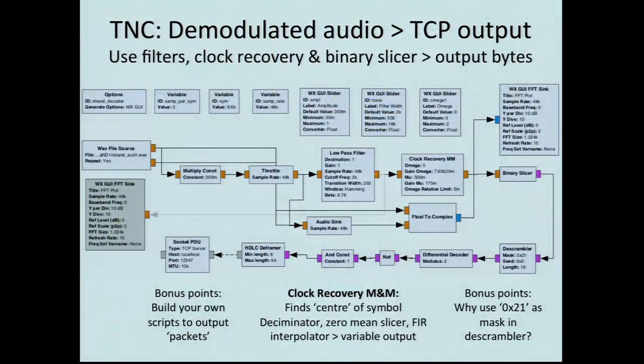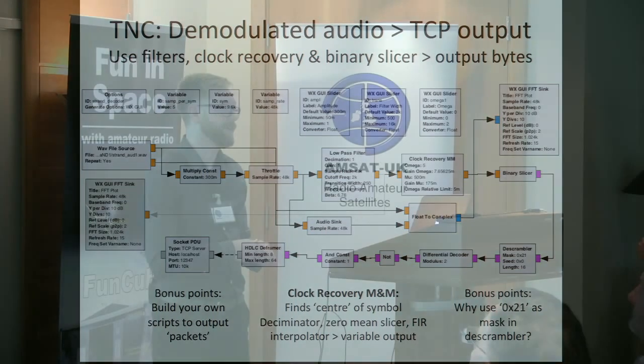Just some examples. The biggest thing that I've worked on is 56 mega samples per second. So you're looking at, at best, hundreds of megabits per second, and I use an FPGA for that. On those FPGAs, I'm doing most of these blocks that you would see in these other systems. I would be putting these into raw VHDL, because that's the performance that I need. If you're looking at just this one, which does 2 megasamples per second, a Raspberry Pi 2 can do it, but as soon as you start adding GUIs, that's where things fall over.